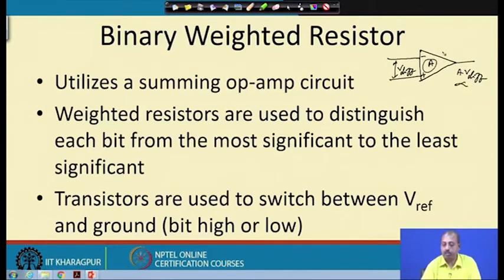On the other hand, we can have some feedback to control the gain. As you know, there are two types of organizations of this amplifier using an op amp. One is called the inverting amplifier, another is called the non-inverting amplifier. They have a particular gain expression which is less than infinity. For example, for the inverting type operational amplifier, the circuit diagram is like this.